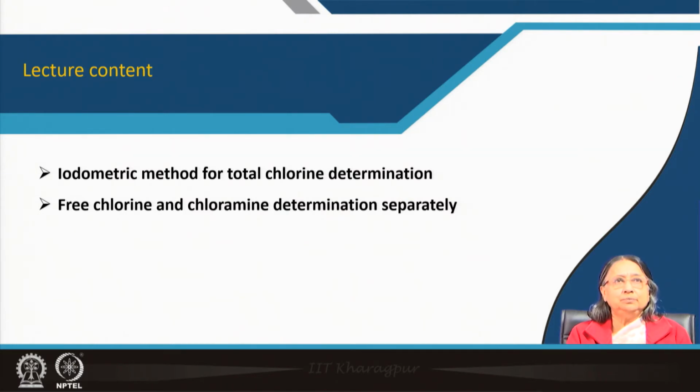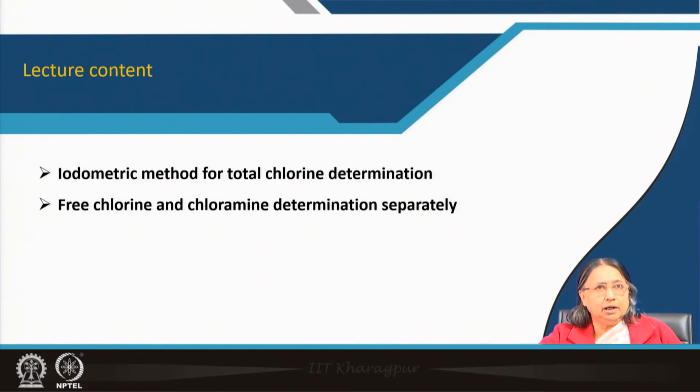These are very important because we have to apply the proper chlorine dose. Otherwise, if it is in excess, it will be a problem, and if the amount is less, then disinfection will not occur. So, this is very important. Now, I will discuss the methods.